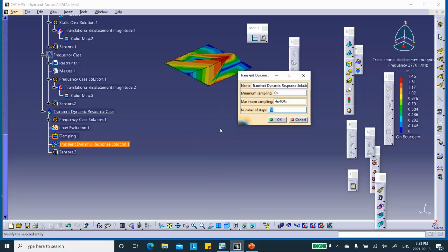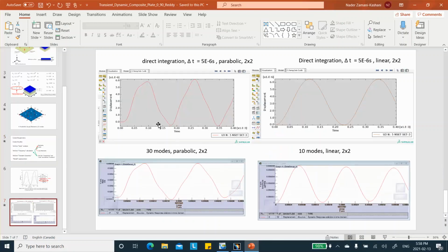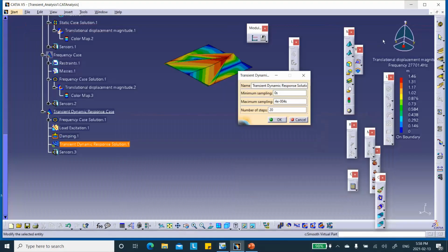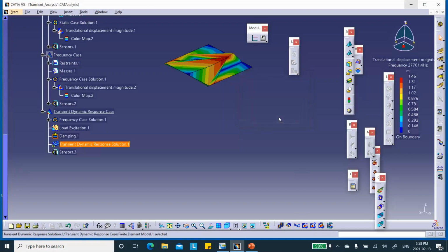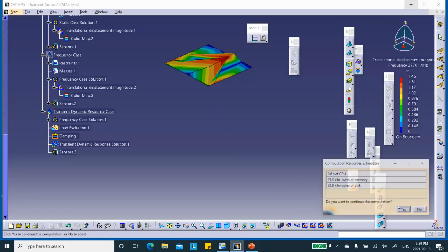If you put too few steps, then the results are okay, but the graphs are going to be jagged. These types of graphs are going to be kind of choppy. So what I'm going to do here is say, okay, I don't know, 80 or 800, and now run it. All. It's going to be very fast.